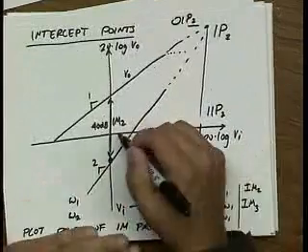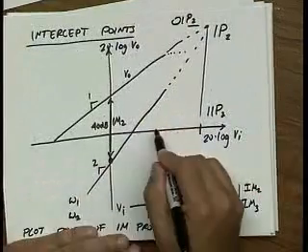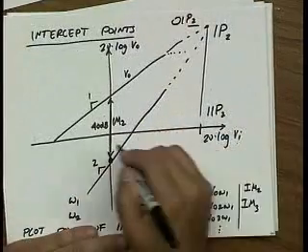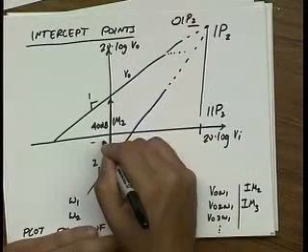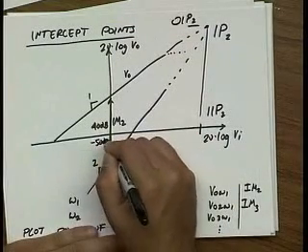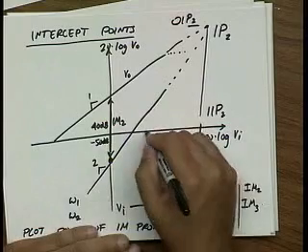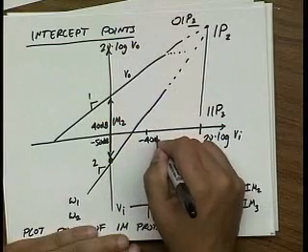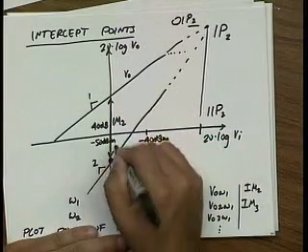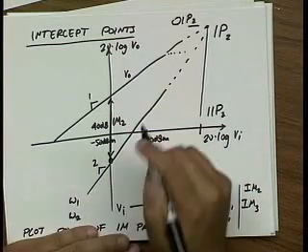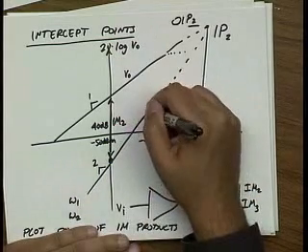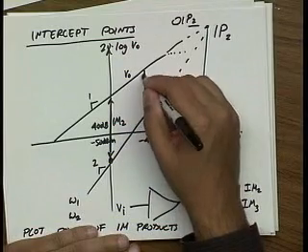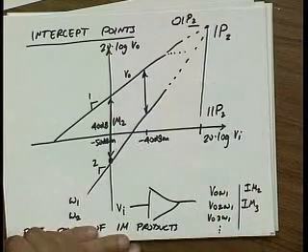What's interesting is that as I change my input power by, let's say, this, for instance, corresponds to minus 50 dBm input power. Let's say I go to minus 40 dBm. Well, that means that my IM2 changes by also 10 dB.